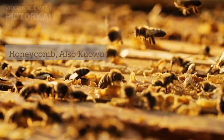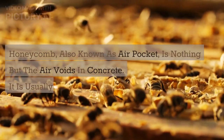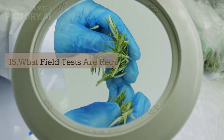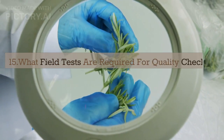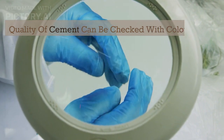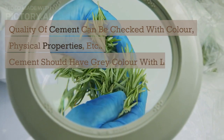Honeycomb, also known as air pocket, is nothing but the air voids in concrete. It is usually formed during concrete casting. 15. What field tests are required for quality check of cement? Quality of cement can be checked with color, physical properties, etc. Cement should have gray color with light greenish shade.